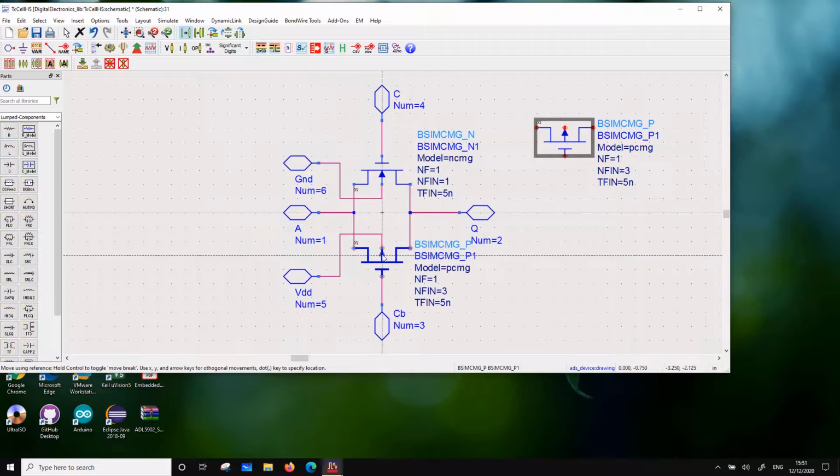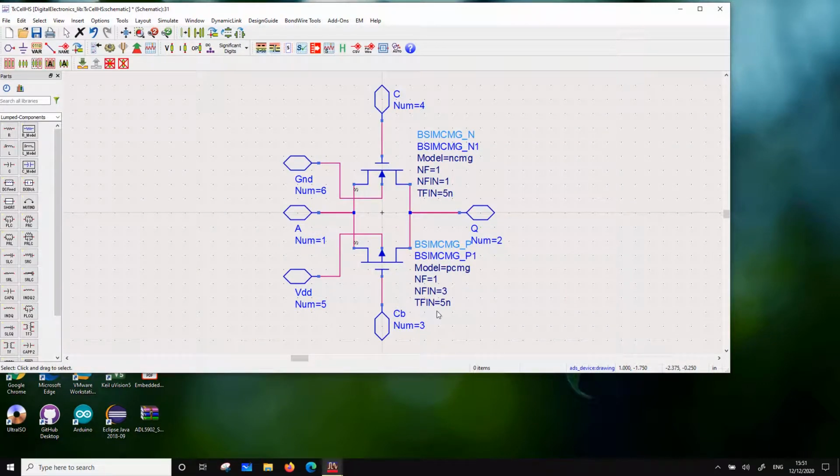Okay, and the source is on the left. Okay, so now the real question becomes, the speed of this transmission gate will depend on the channel resistance and what capacitance it is going to drive. So the capacitance would usually be the gate capacitance of the gate it is going to drive. If you have a very large channel resistance, then the circuit is going to become slower. For that reason, I'm going to increase this to, let's say, 2, and increase this to 4. So this is to reduce the RC time constant for the delay, right? So this is done.